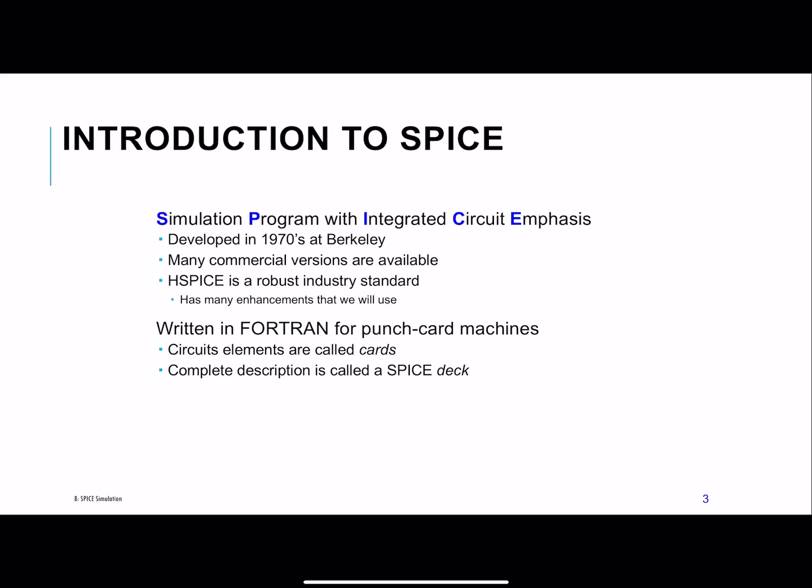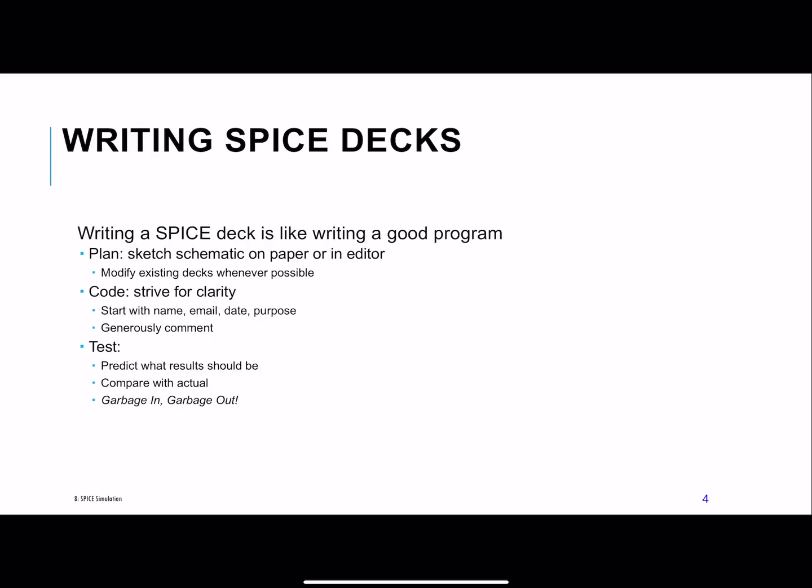And this basically is a full simulation. What you do is you create your schematic or netlist in the program, and then you give it the model file. So I put up a model file for the 180 nanometer TSMC process.